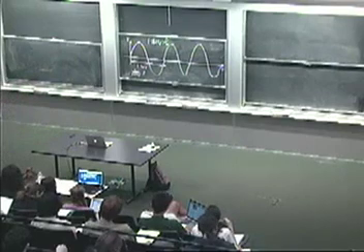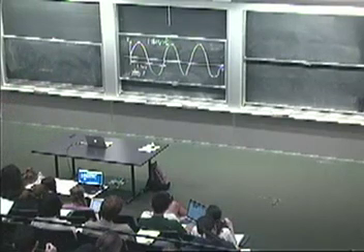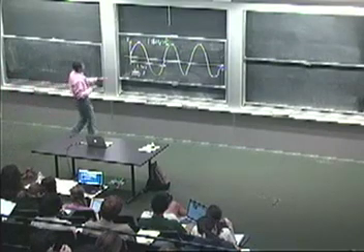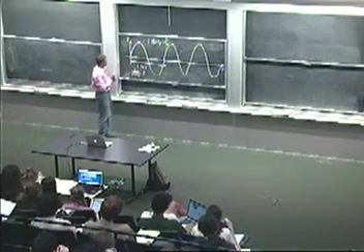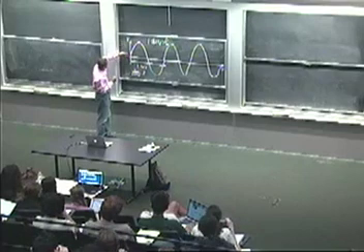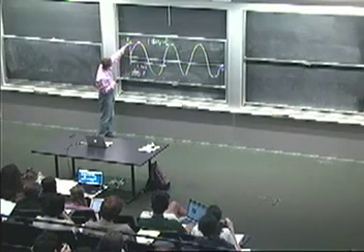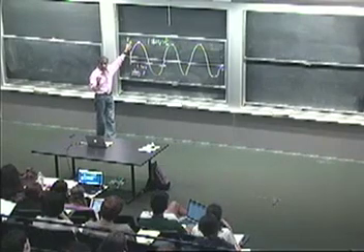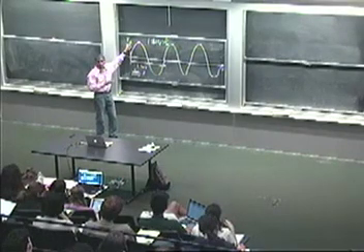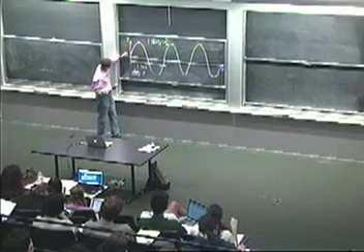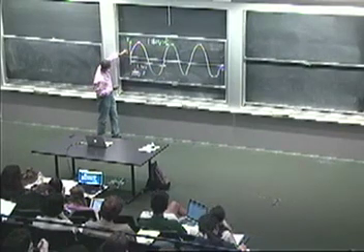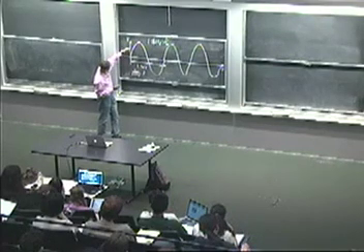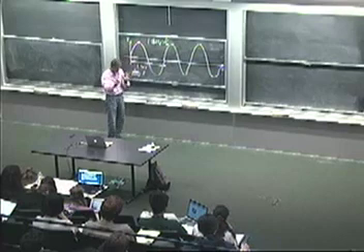So if I were to send a pure sinusoid at the receiver, the way the sinusoid is transmitted is by providing these samples, each sample being equal to this voltage value picked from this curve, and I send each of those samples. Each of those in our implementation is a 32-bit floating point number. I pick a number here, 0, and then I pick something here, which is the value of the sinusoid at this point in time, and this, and this, and this, and all the way down. And I send those samples.